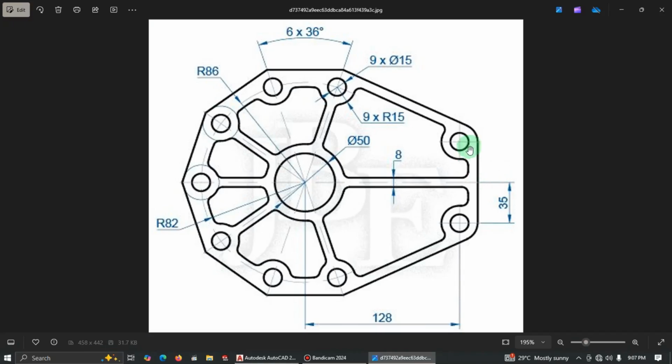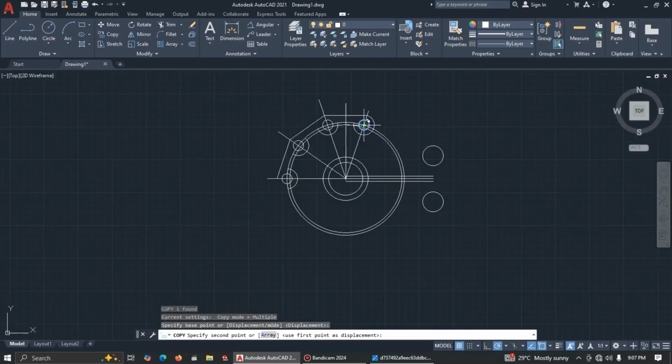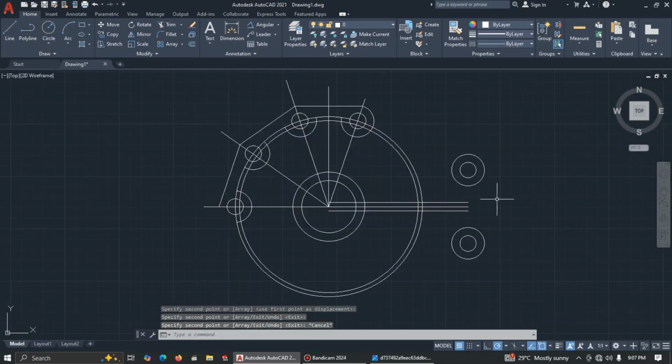Now you can mirror, see, let's mirror from the center point. Good. Erase source object, just click no. Now let's copy this. Now from the center, I'll just leave it here and here. Good.